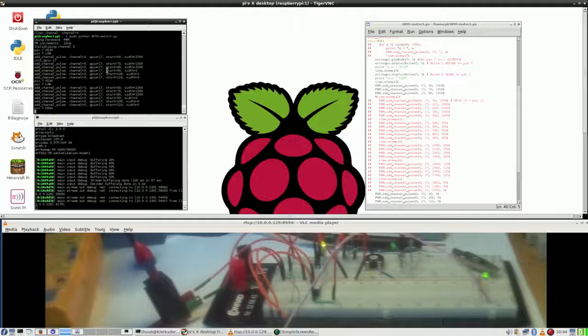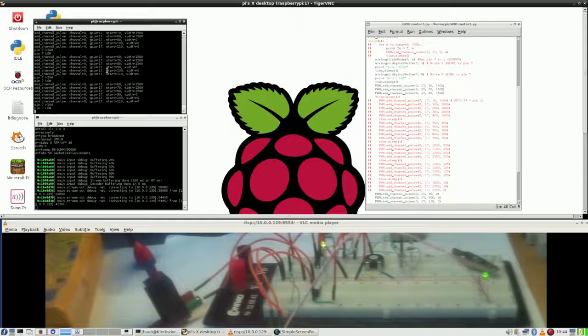Alright, time for a frequency measurement then. Right at the transistor. Well, the wire then. Alright, that shows absolutely nothing. So I will take the other wire and do exactly the same.